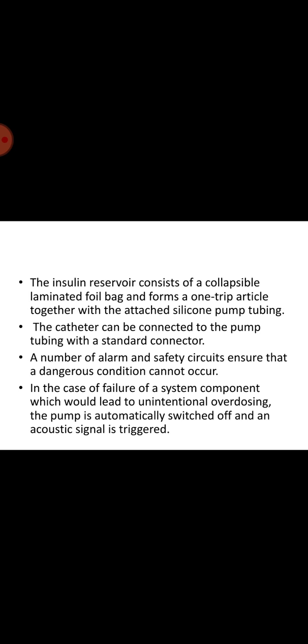A very important parameter in such pumps is the accuracy of the pump delivery rate, which refers to the average rate per complete revolution of the pumping head. The delivery rate is influenced by electronic component tolerances and drifts, which can be limited to plus or minus 0.5% by proper selection of components.